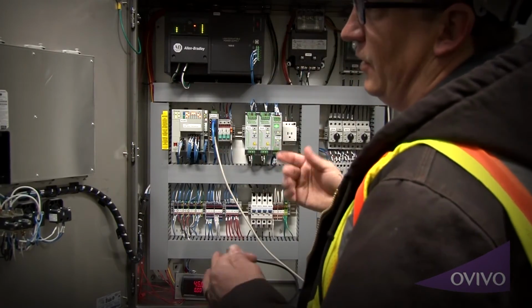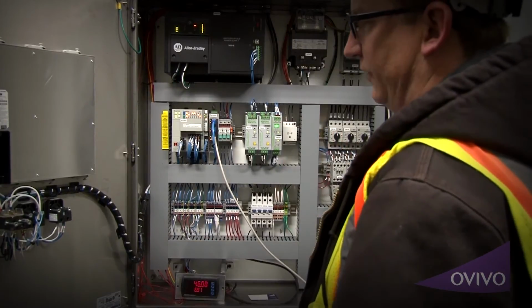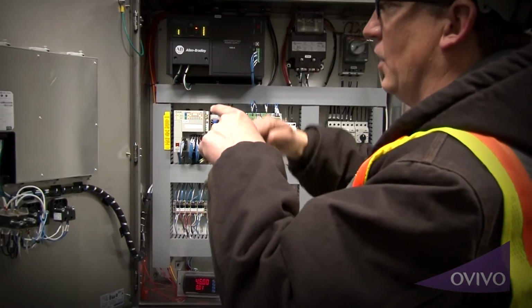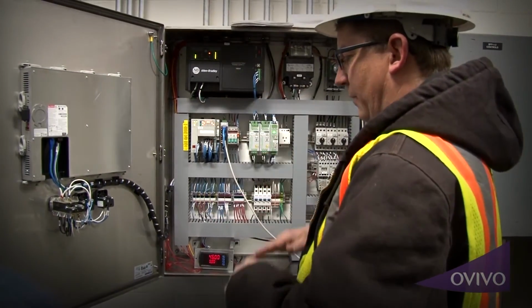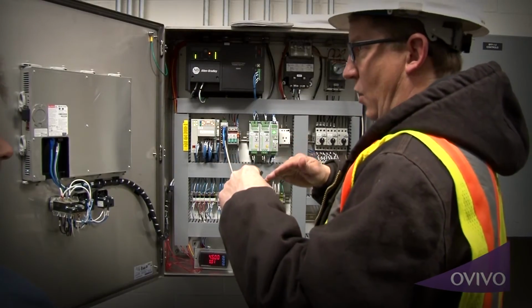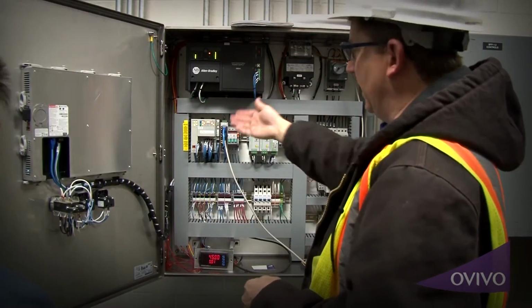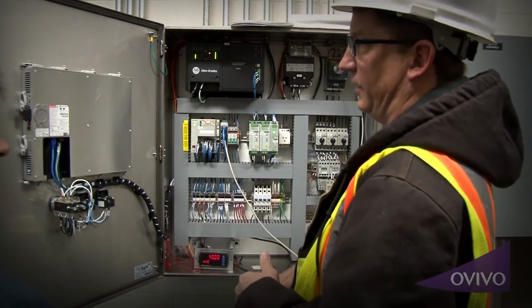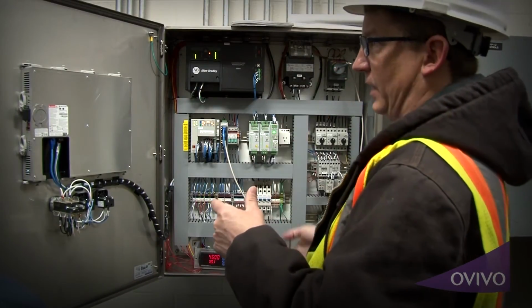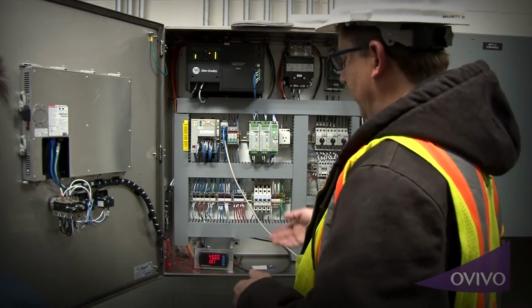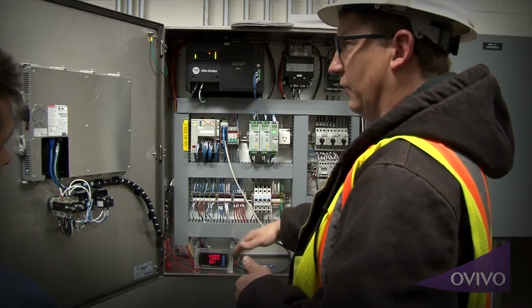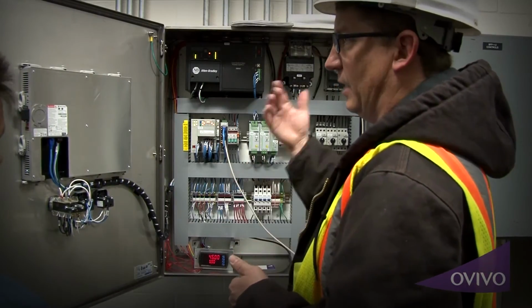Now keep in mind, because the tank is round, as it goes up, the bottom part is going to fill up slower than the top part. So the PLC recognizes that and does calculations to make the curve fit volume-wise. In the lower levels, yes, that's going to read somewhat true, but in the upper levels it's not.